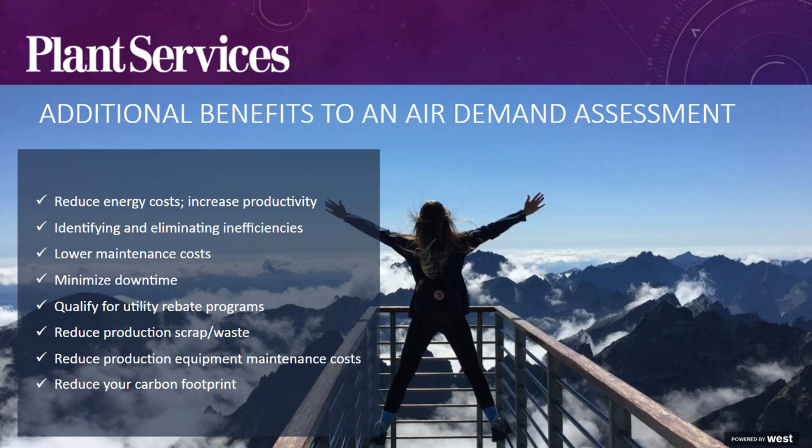Using air audits to help qualify for utility rebate programs and pay for system upgrades. Another great opportunity there. Product scrap and waste can be improved by providing stable operating pressure to the points of use. Production equipment maintenance costs can also be lowered through improved air quality, by assessing whether existing air treatment is sufficiently selected and sized to meet the required air quality. So that should be part of every audit.